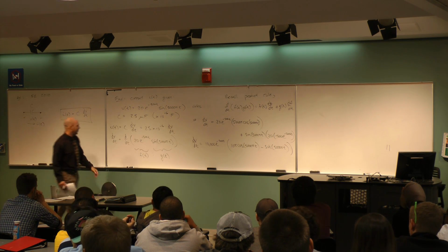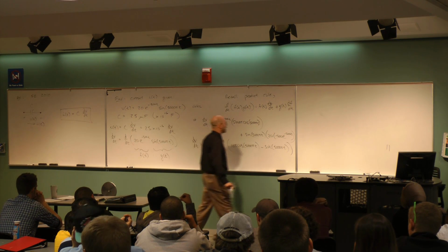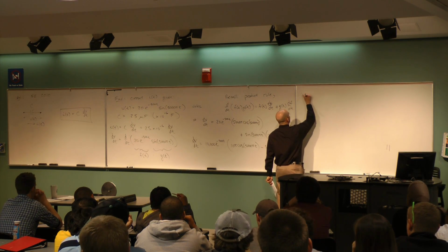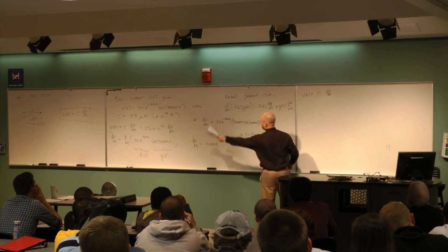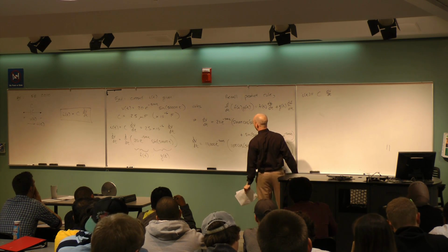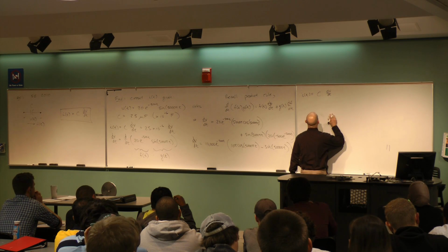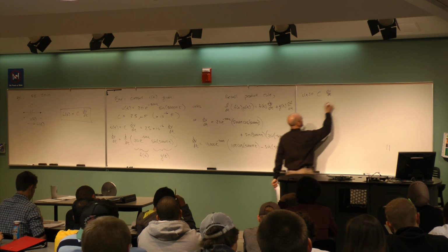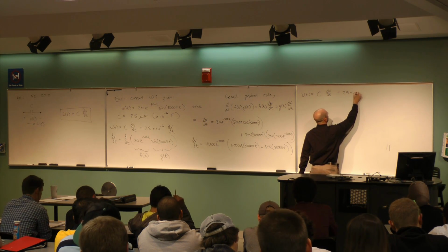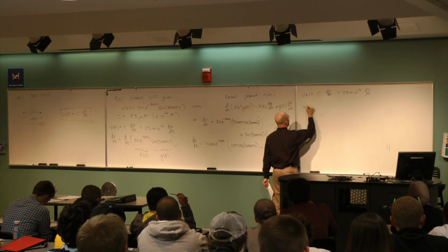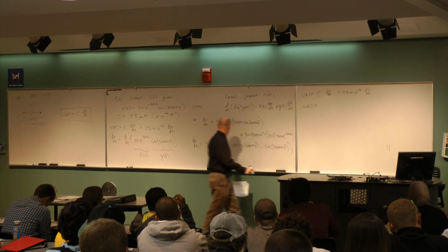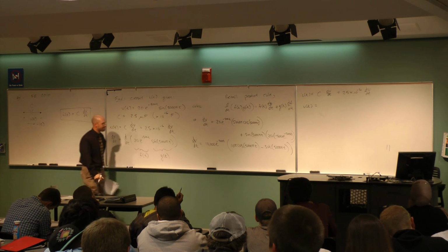Okay, but I have one more step, right, which is to get the I need C dV dt. So I of t is C dV dt. Right, and so I need to multiply by 25 times 10 to the minus 6. Okay, and so, right, this is 25 times 10 to the minus 6 times what we just got. So when I take 25 times 10 to the minus 6 and I multiply that by 10,000, what do I get?